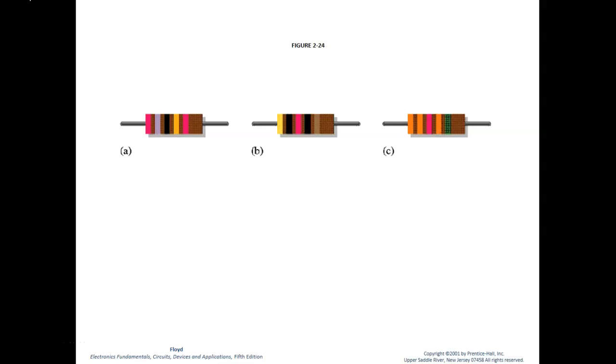So the way you're getting your tolerance, there's a couple different ways. 402 times 1%, you can do it like times 1% in your calculator, or you can do it as 0.01. That's just translating it from percentage to decimal, right? Then to get your upper and lower limits, you just add and subtract it back in.